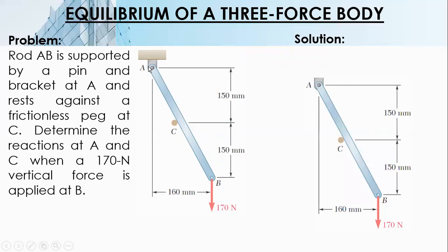So, this is our rigid body. We will cut and then isolate this. The unknown forces here, we have RC. Now, the reaction at C is perpendicular to the ACB member. Okay, rod EB, rod EB. Perpendicular. And then you have RA and then RB.